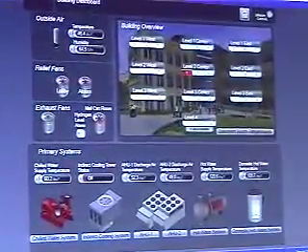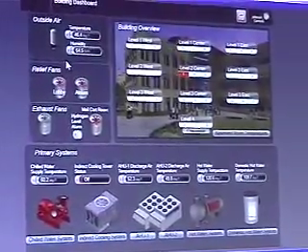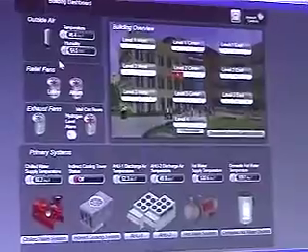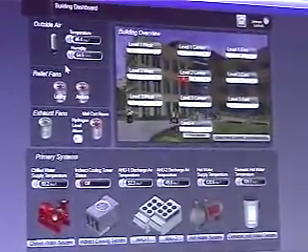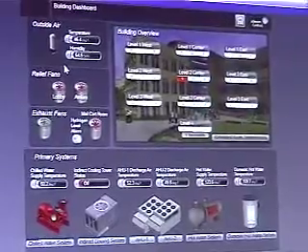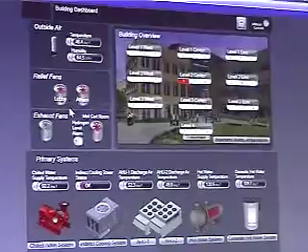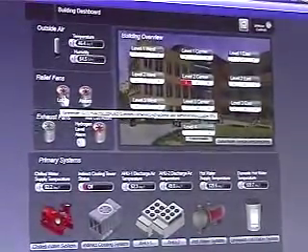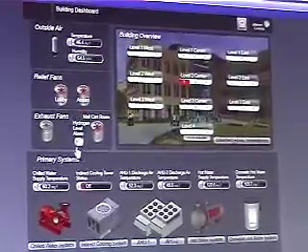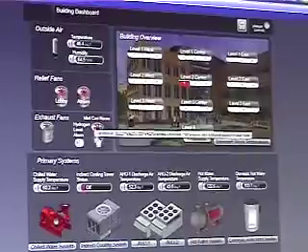potential issues. To start through, this is your outside air temperature and humidity sensor. This is located on the building as we discussed last time, and this is the one outside air temperature and humidity for the building, so it is shared globally throughout the different processes. Down here you have your relief fans. You can see right here where it's spinning, that means it's on. This is stationary in red, so it's off. Then you have your exhaust fans, hydrogen sensor in the mailroom.